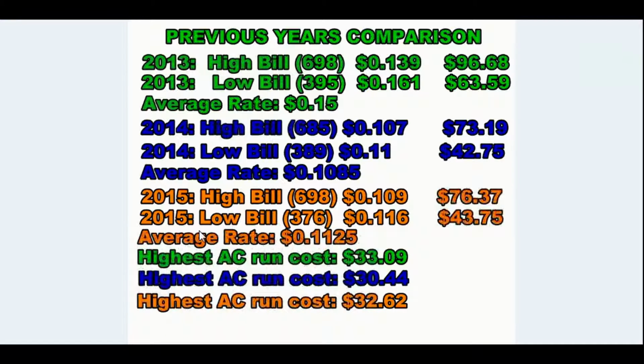Some of those far zones, way over on the other side of the house, can approach 85. But one thing you have to realize is you're running at least one zone 24/7. You're going to get characteristics where it's pulling humidity out of the home, and so on. Really rarely would I shut the system completely off. I'm always running it. About the only time I shut it off is if it's broken.